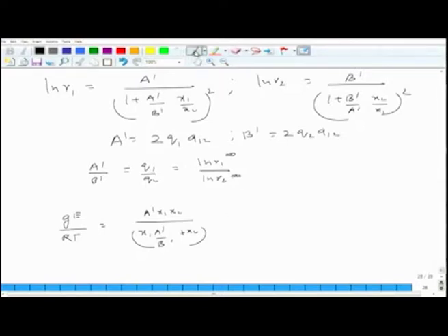Or we use it in this form. Okay, this is nothing but a two constant or two parameter expression, or two parameter theory, we say. So this is the Van Laar expression. You can easily make use of this for benzene isooctane as well as n-propanol and water. It works very well. Okay, so it captures the complexity of that nature of dissimilarity.